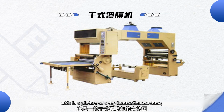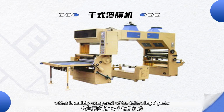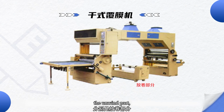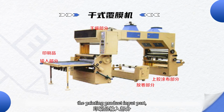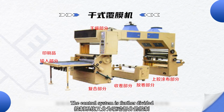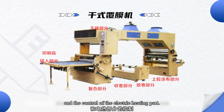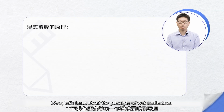This is a picture of a dry lamination machine, which is mainly composed of the following 7 parts: the unwind part, the adhesive part, the drying part, the printing product input part, the laminating part, the rewind part, and the control system. The control system is further divided into the control of the drive part and the control of the electric heating part. Now, let's learn about the principle of wet lamination.